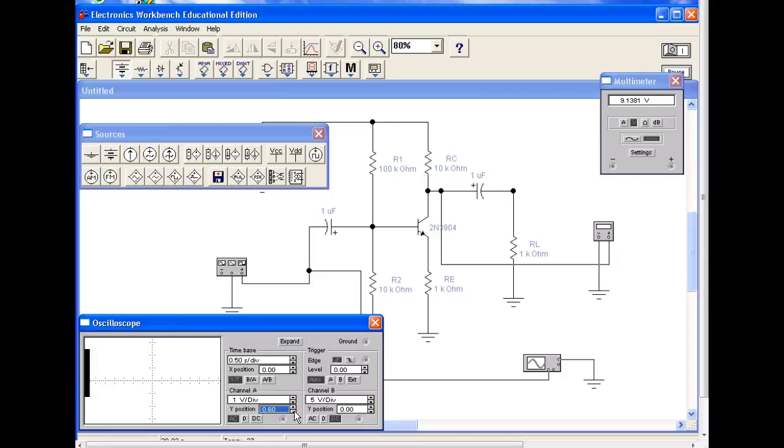Okay, so now I'm seeing a solid bar. What does it mean about my oscilloscope? It means I'm going too slow, right? So I'm going to decrease the time per division. Okay, so there's our AC coming in. And this guy here don't want to trigger, but we can get a pretty good idea what this thing is.